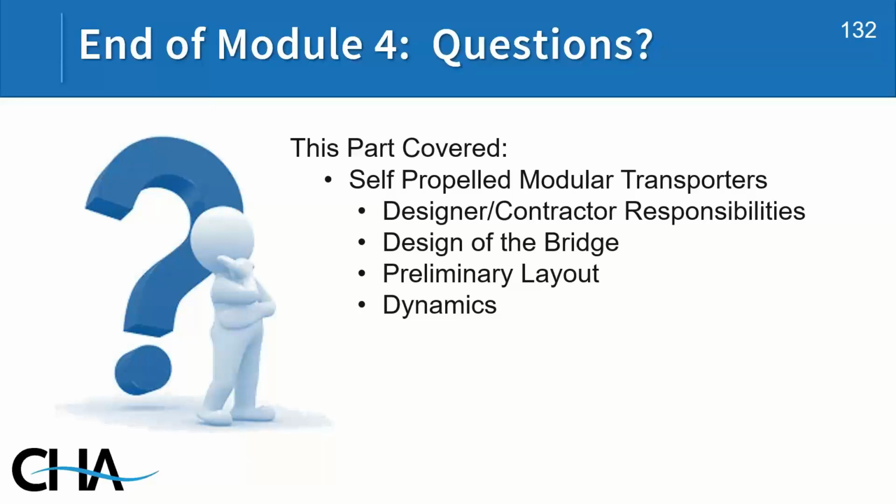Again, we're dealing with a significant number of axles and spreading the load out significantly. If there is concern about utilities, we have seen projects where steel plating has been put down on the road to even further spread out the load from the SPMT to the pavement and the utilities underneath. In worst case scenarios, more significant crane mats and bridging can also be used.